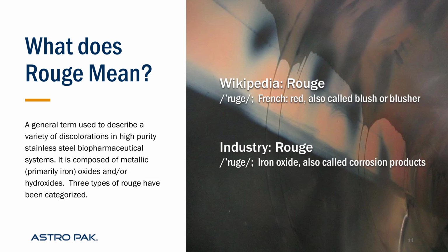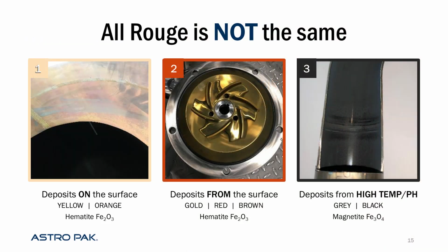They appear the same when you take them under an SEM and analyze the elements. You see iron and oxygen. I consider the corrosion product of carbon steel different than the corrosion product of stainless steel, although those are both pretty similar iron oxides. But to me, rust and rouge on stainless steel is pretty interchangeable. Industry has classified, I haven't said defined there, but classified, 3 different types of rouge.